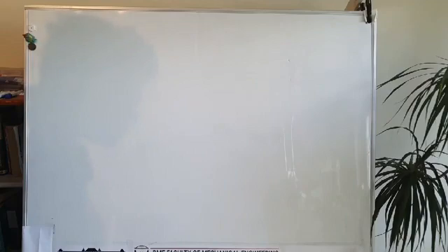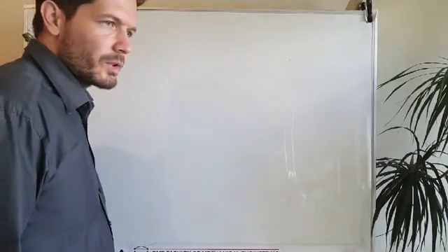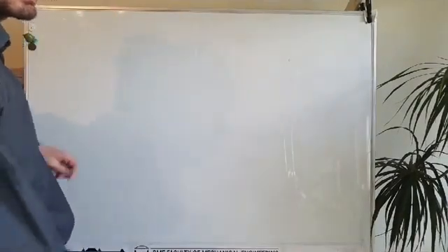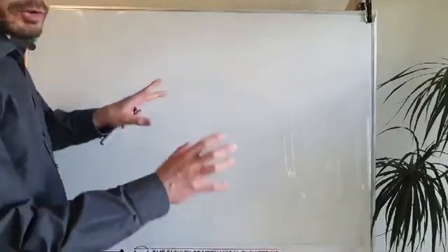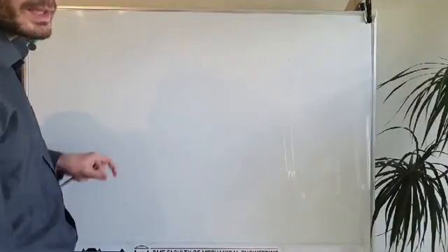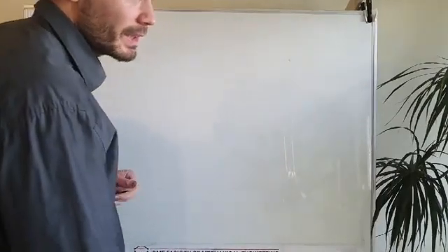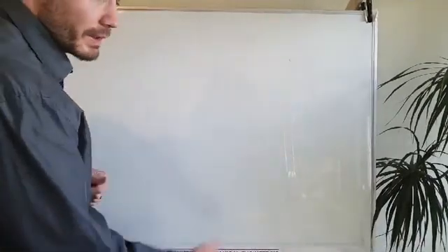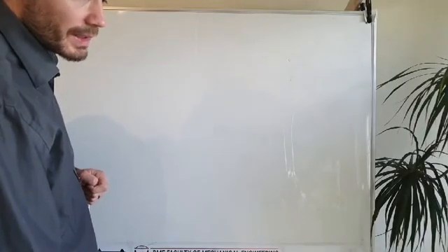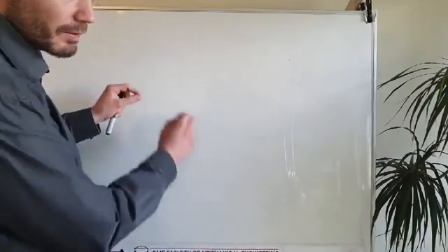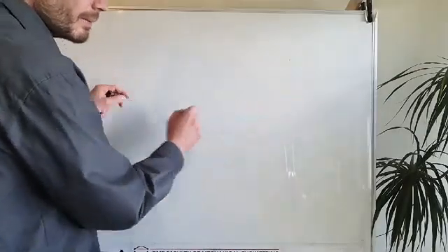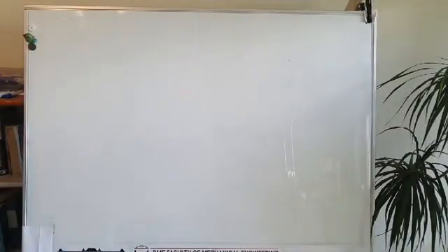And what we also introduced is the so-called Aronhold-Kennedy theorem, which says that if we have three rigid bodies and they are moving in the plane, so they are performing planar motion, then there will be three instantaneous relative center of velocities, and they will be collinear, so they will be situated on one single straight line. So that is what we have so far.